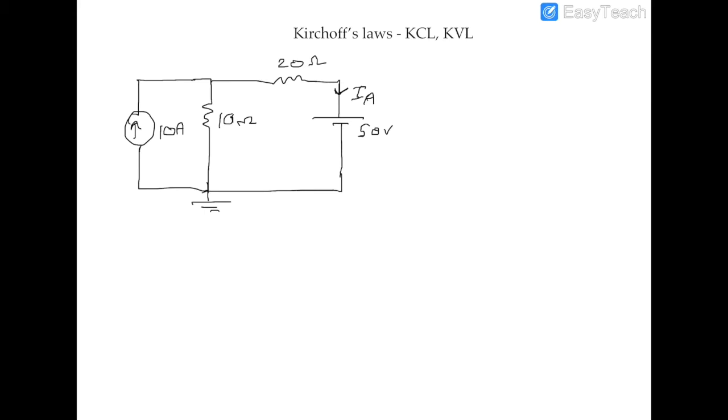Since you saw in the last problem, this problem is also we're gonna use KCL. All right, so there's these three ends connected together. So you have a current source, and you have a resistor, and also you have a battery, which is all connected together, and one end is grounded. And then you're doing your circuit analysis there.